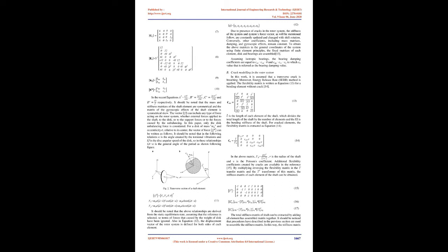Zakowski, 2017, used modal analysis to simulate the behavior of a non-rotating Jeffcott cracked rotor. Simulation results presented changes in natural frequencies of the system with the changing angular position of the rotor. Those changes were observed as doubled natural frequency peaks in the rotor's frequency responses. They appeared only for the cracked rotor and could be explained by shaft stiffness changes due to the opening and closing of crack faces under gravity.